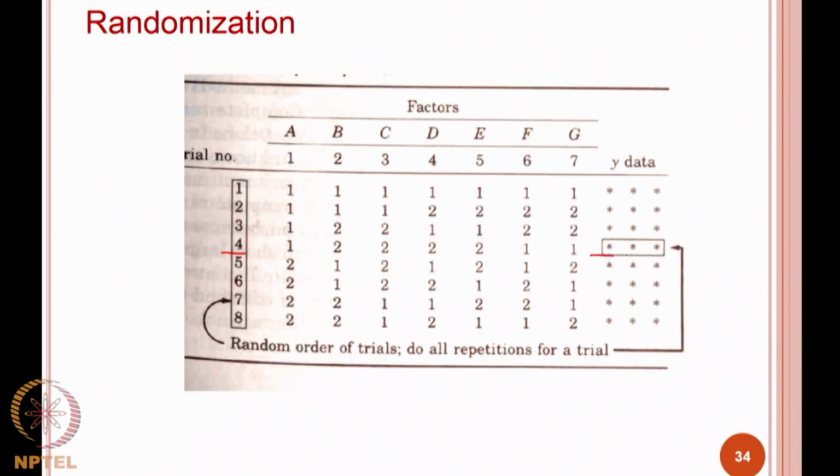So, what you do is you fix a particular experiment level, in this case 4, which means one of the conditions is fixed, and then you repeat those experiments 3 times. Imagine that I am trying to do different studies on different types of grips in the tensile test that I am talking about. Putting the grips into the holder is a big problem. It takes a considerable amount of time. Your tests will take a few minutes, but getting the grips in and making sure they are aligned takes a while.